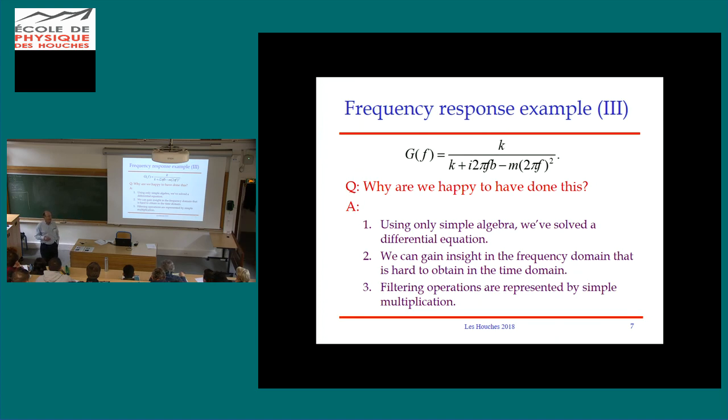And in case the wonderfulness of that feature is not obvious, let me state what we would have to do if we were trying to do all our physics in the time domain. If I had two linear systems cascaded, and I were trying to describe them in the time domain, I'd say, well, the filtering operation of the first one is the convolution integral of the input function of time with a deterministic function of time called the impulse response.